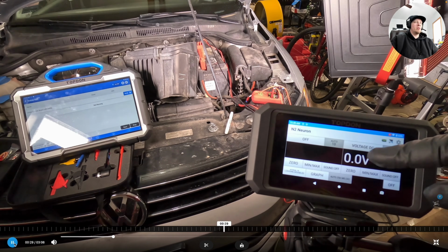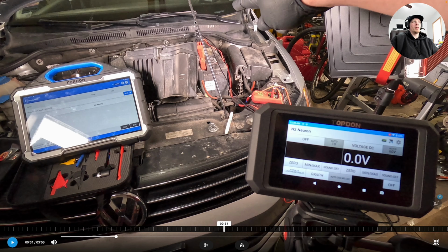So we are plugged in. We're checking the first wire. Again, we've got our negative black lead plugged in over here at the battery and plugged into C for common. And then we've got our red lead for V for voltage plugged in at the V terminal. And then we are probing one of the headlight connector terminals.